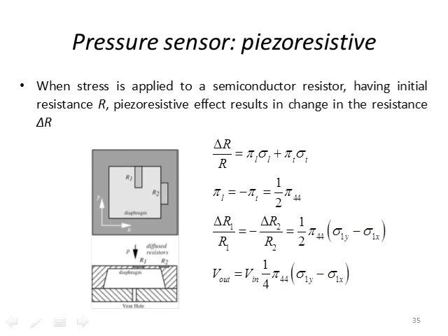Then it's going to have components for resistance change in the longitudinal direction and the transverse direction, so X and Y directions. And then depending on the material, it will have different properties depending on whether you stretch it in the Y direction or stretch it in the X direction. And you can engineer these systems to give you a particular type of resistance change depending on the strain that you apply to the material.